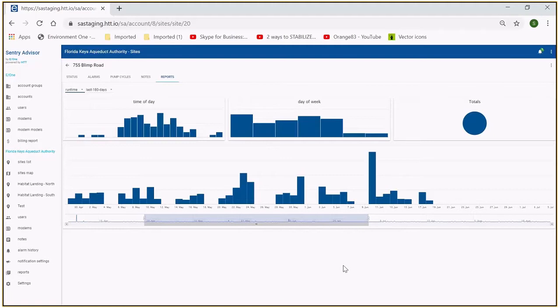And from there, now we can see, hey, we have one pump doing all the work, one pump not doing anything. There have been no alarms recorded on the site, so now the power is in our hands. We can choose to notify the customer and explain to them what we're seeing. We're seeing data come through from one pump only. There's a high likelihood that one pump in this system is down. How would you guys like us to handle it?